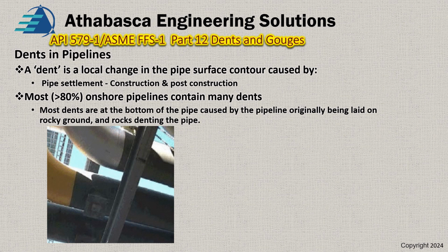The first slide I show you is an experience that I had on a pipe rack. I've seen cases where the wear pad or the pipe shoe has been misinstalled or it's moved more than necessary, and the pipe has fallen off the pipe support, which is shown to the left here, and that's caused local denting in the pipe. I've also seen this where the structural frame was inadequately gusseted, and it collapsed and caused denting. So those are common problems.